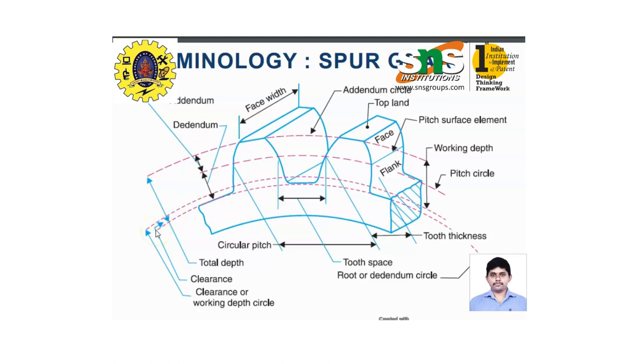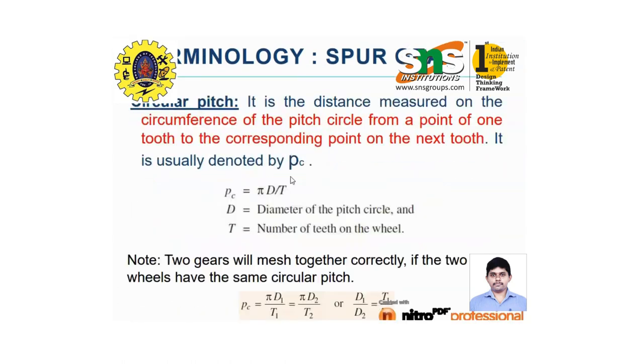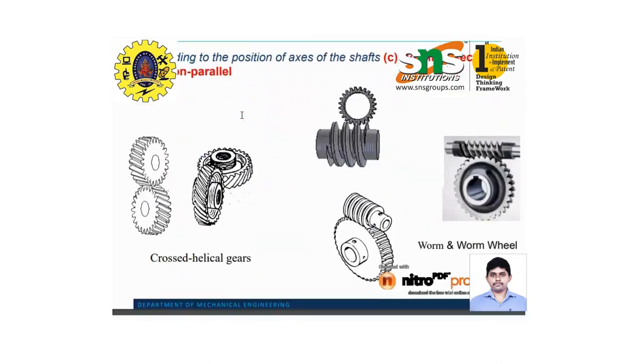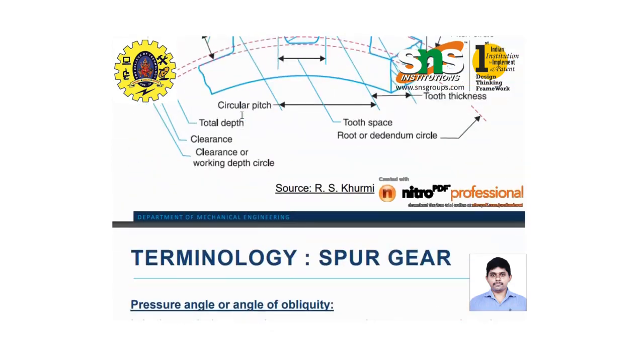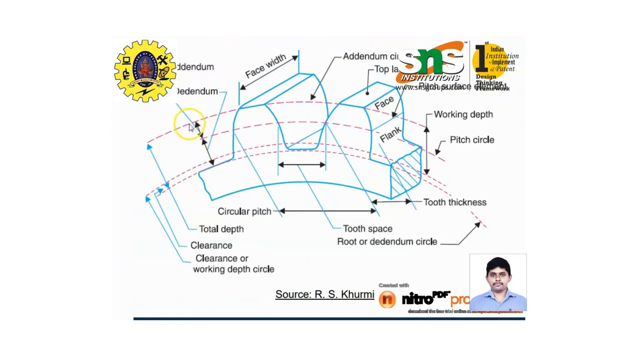If you take the addendum, it is a line that, instead of flowing through the bottom, we just represent as the addendum. And the dedendum has been represented in two different ways. The first one, this circle is the addendum, which means the distance from the mid of the tooth to the top of the tooth is the addendum, whereas from the mid of the tooth to the bottom of the tooth is called the dedendum. And here, beside the tooth, these are the face and the flank.